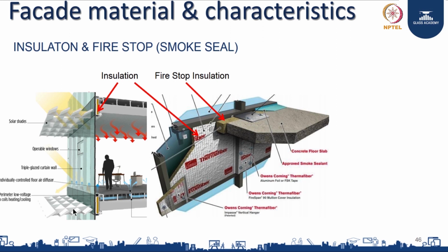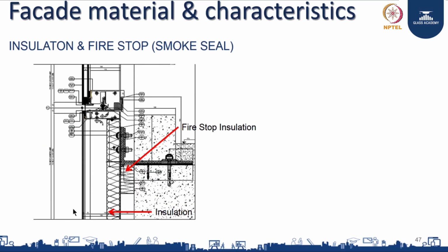So they use that and treat the joints properly with the proper design. So when you design a system, these are all the factors you have to take care of. It is not just simply going on. Now you see this gap here, whatever I showed in the previous video. There is a gap between the wall and the mother slab or mother building. This gap is now filled with the fire insulation, fire stop insulation or smoke seal, whatever we call it.